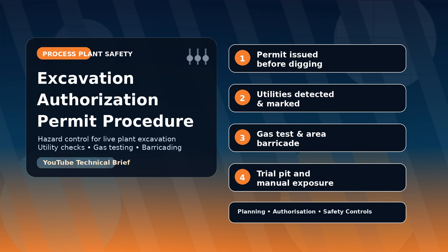Then sometimes the civil team or the safety team, especially the refinery safety engineer or team, you may also need to get approval from. The operation team also needs to approve, and the maintenance team as well, because as you're going to excavate in a gas plant, you don't know whether there could be some toxic gases present below the ground. Once you excavate the soil, there could be some toxic gases there. So they may tell you to do some kind of gas testing before you start your excavation. They also write in the permit that you cannot start the excavation like that.